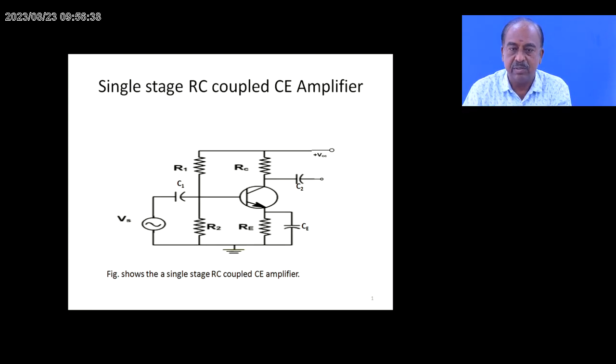In this circuit, four different types of resistors are there. One is R1, another one is R2. These two behave as a potential divider arrangement for dividing our given DC voltage to the required level. R2 gives a very small voltage that will be used as the input voltage.